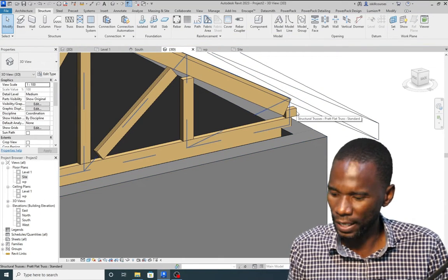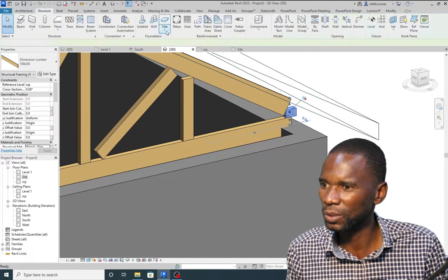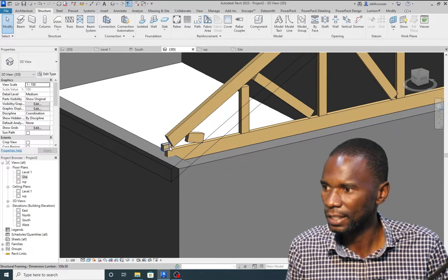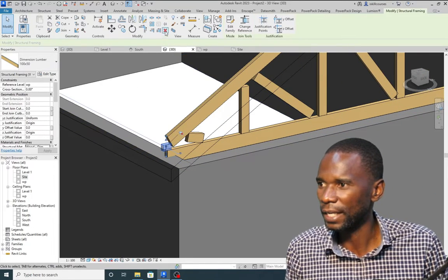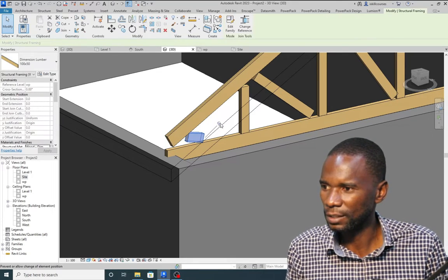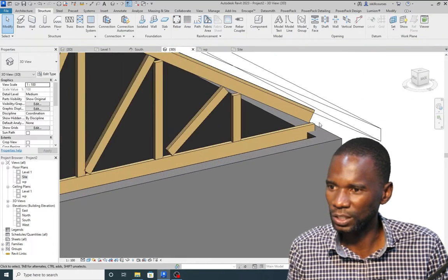You can also go at the end there, tab, select that member and pin it, and you just want to clean up those smaller pieces at the end there. Tab, select that one, and I'll continue doing this. I also want to tab, select that member and pin it, and delete that one, as you can see.